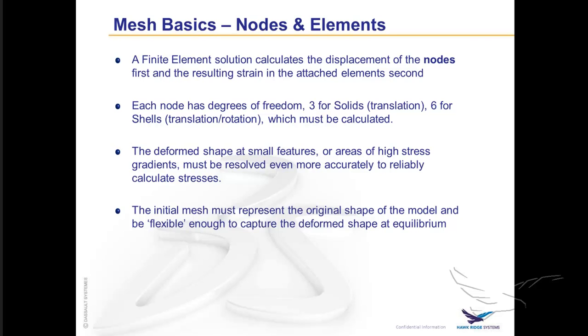Also, you can think of a mesh as having to map the initial and also the final shape after the loading has taken place. And in areas where we expect high stress gradients, maybe smaller features, we need to resolve these areas more accurately to reliably calculate these stress results.